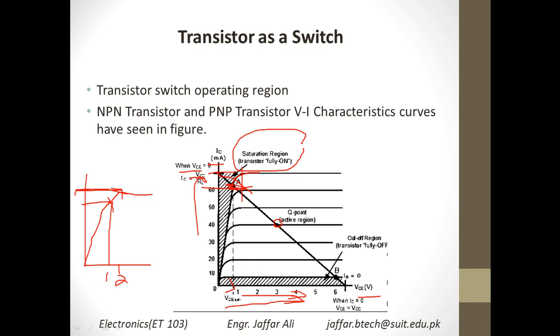Do look at the data sheet before actually providing higher voltage to any transistor or any device. You have to look at the maximum voltage that that electrical component can receive, and do not go beyond that limit, because it will definitely create trouble for yourself and for that device as well.